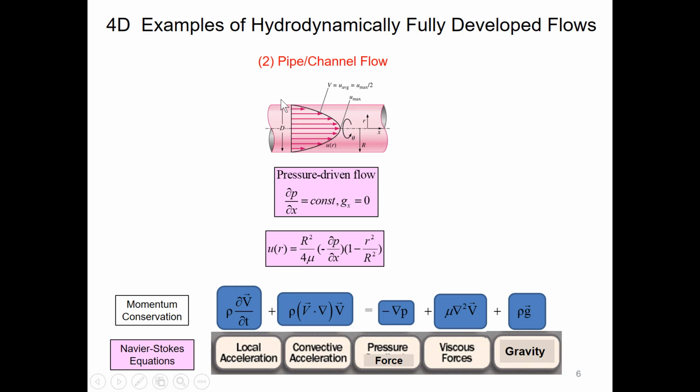Second, for a channel flow or a pipe flow, it is pressure driven, which is the pressure force overcomes the viscous force to push the flow moving forward. And the pressure derivative in the flow direction x is constant.